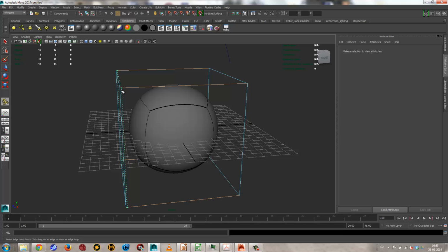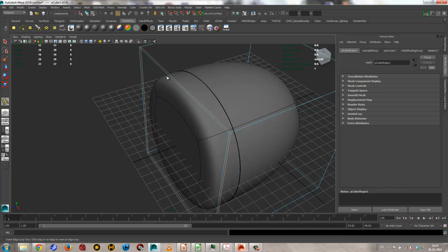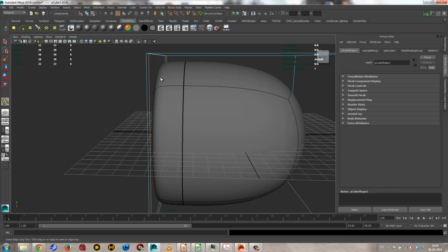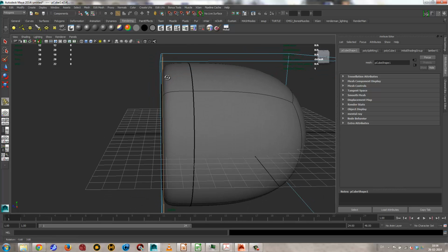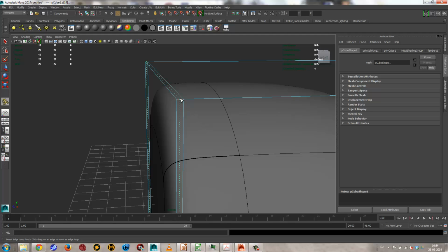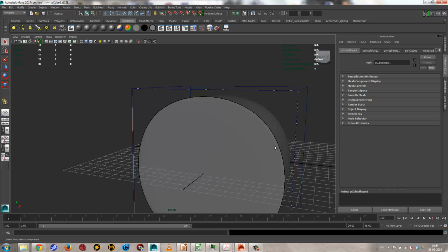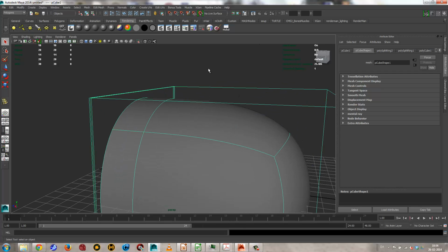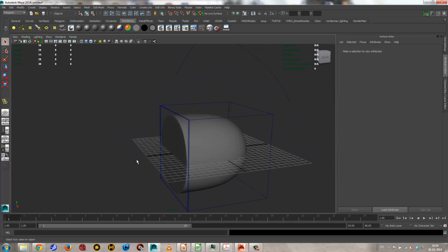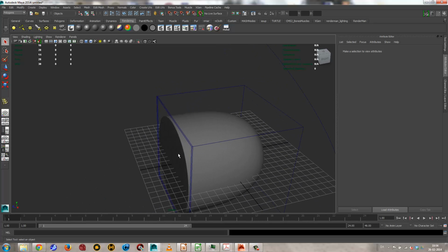So if I drag it over here, this will essentially mean that I have 2 points close together. So I get something that is tighter, but not a totally hard line. If I then add another one in between here and let go, you can see I get something that is very, very close to a sharp corner because of this. So that way you can control Catmull-Clark surfaces is by inserting extra detail.